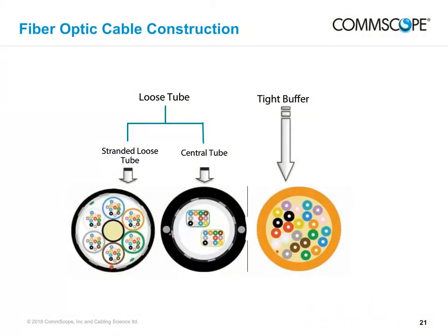In addition to the 2 main types of fiber, single-mode and multimode, there are also 2 main types of fiber cable construction, loose tube and tight buffered. This illustration shows the loose tube and tight buffered cable designs. In the tight buffered type, the protective tube or buffer holds the fibers inside close together, giving them little freedom to move in relation to each other or the buffer.